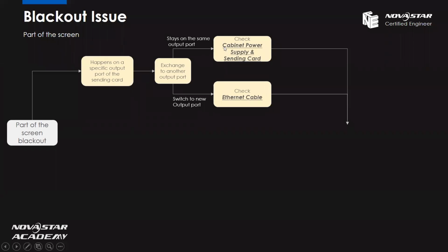And also, we need to check the power supply. It is because if there is something wrong with the cabinet power supply, then the receiving card cannot get any signal from the sending card. So the screen is also black.